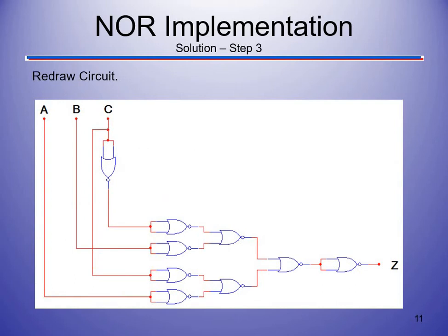Okay, so similarly to the NAND, this one we may or may not have some double inversions. We're going to have to take a look and analyze it a little bit closer so that you can see. Remember, a double inversion is where we have something going into one of the NORs, and then it goes into another NOR. So eventually we're getting back out the same signal that we sent in. So it's kind of redundant, so we call it a double inversion.